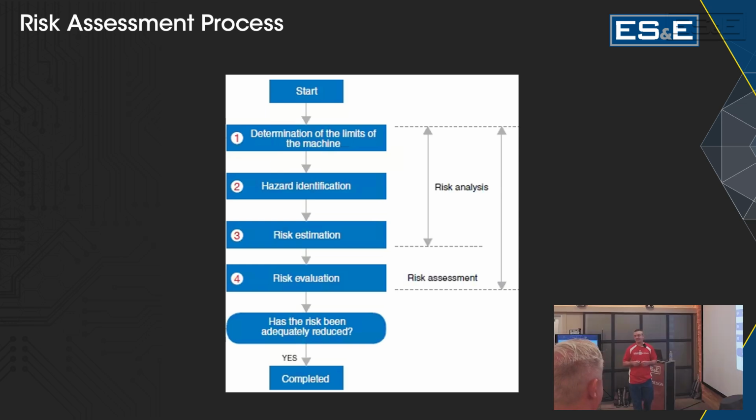Yeah, initially, like I said, you evaluate the machine with no guards in place. The machine is what it is, and if you're in the design phase, you may have the opportunity to design the hazard out totally. You may choose to incorporate that robot. It may pay for itself based on what you're trying to do. Again, a lot of times safety is dealt with after the fact, so it's a little bit more of a challenge to deal with then, and you're also kind of stuck with what you got. If you can design it out in the beginning, obviously you're a lot better off.